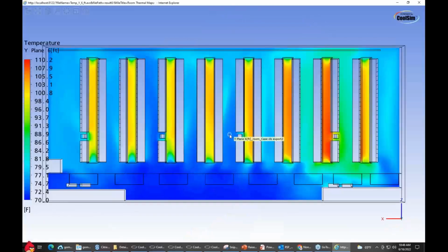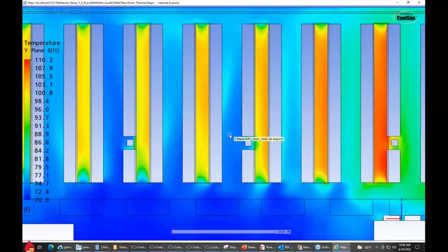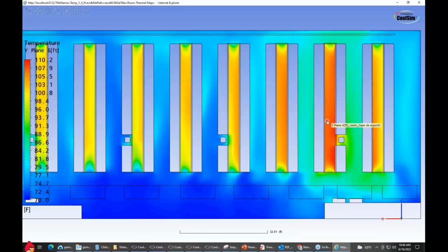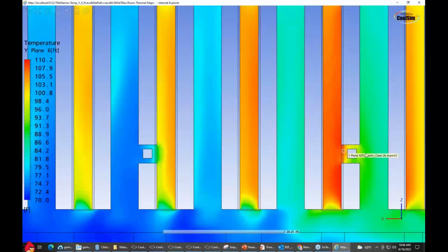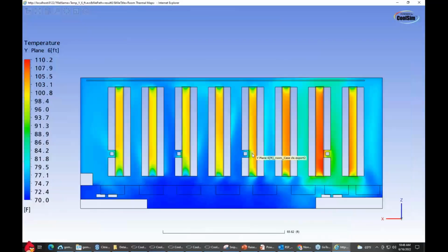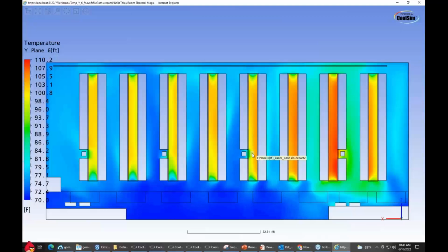Let's take a look at the Y gradient, and let's turn off perspective, and you can see here that you want a positive gradient. Well, here we're looking at temperature. So you want the hot aisles hot, cold aisles cold. This one's got problems. It's leaking around this section. So problems in the thermal and problems in pressure, same issue.